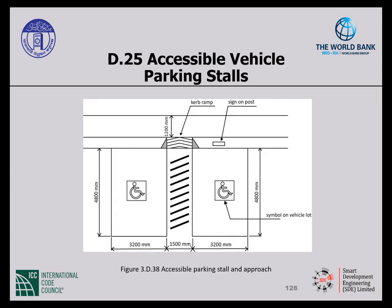Accessible parking stalls should be a minimum 3,200 millimeters wide by a minimum 4,800 millimeters deep. Access aisles should be 1,500 millimeters wide by the same depth, 4,800 millimeters. You should also provide a symbol of accessibility on the surface of the parking space, and that should be white on a blue background of either 1,000 by 1,000 millimeters or 1,500 by 1,500 millimeters.